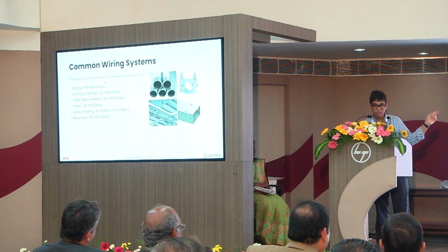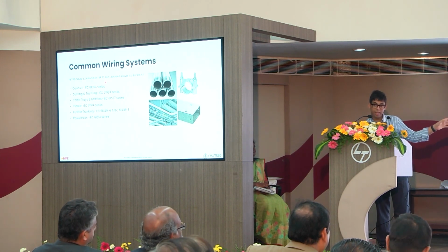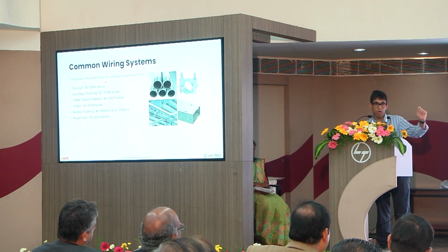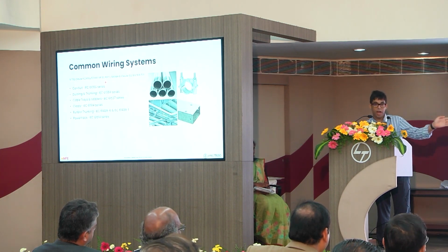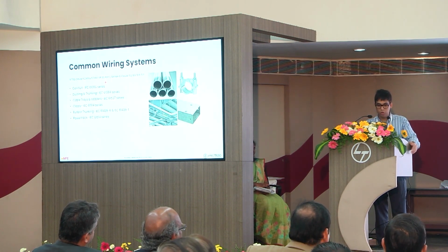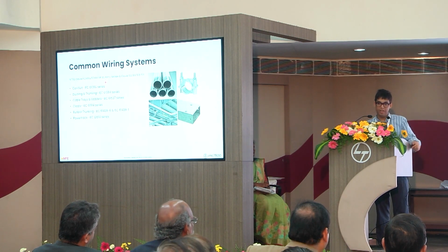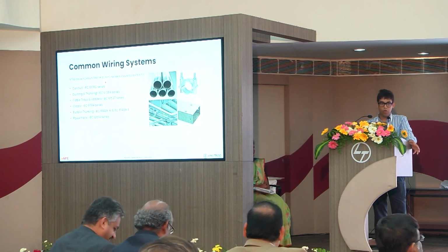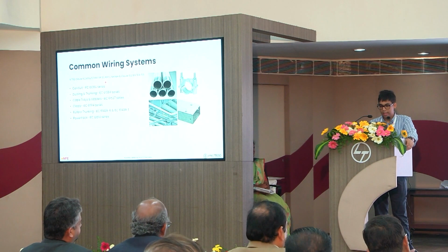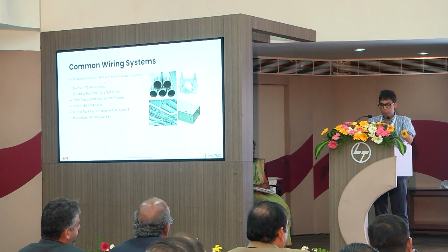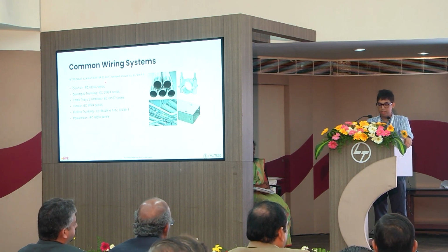Note, a lot of these IS standards exist, but they're very old. So for the purpose of the presentation, I have made reference to IEC standards, but please, when you go back on Manak Online, a lot of these are now IS/IEC. They're just a standard that's directly been approved as IS. So if you put these numbers in, you'll find the relevant IS standard and you can check for conformity with that manufacturer. And it's very important for the actual products that we select to actually meet these requirements, because that's the only way we can achieve the overall performance requirements mentioned in IS 732 and SP30.